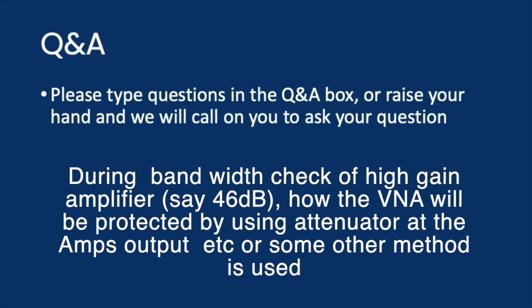And typically on our higher end analyzers, we have direct access ports where you would use an external coupler and take the forward going wave, bring that into the reference input, let's say for port one, the measurement or the reflected wave into the measurement input for port one. So that would go directly to the VNA receivers. And same thing for the coupler at the output of your device under test.